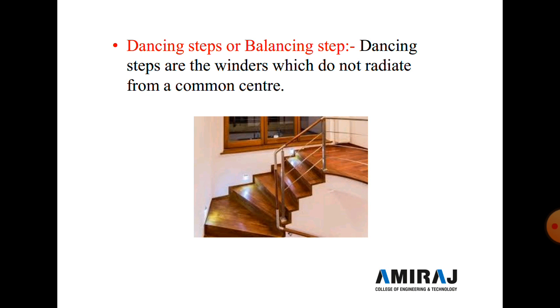Now next is the dancing step or balancing step. Dancing steps are those which do not radiate from a common center. They are generally provided to change the direction of the step, and in a dancing step all the steps are not the same size; at the corner side, the size of the step is changed.